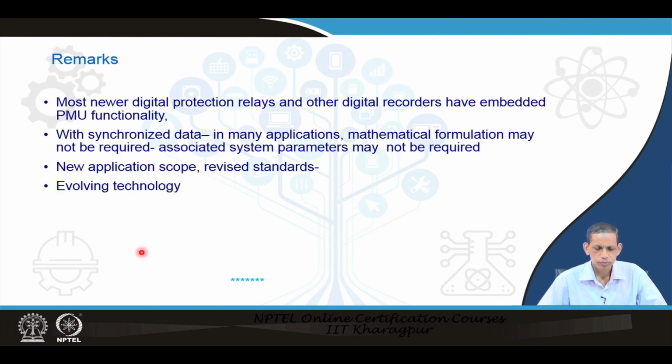So, overall we see that the phasor measurement unit, which provides time synchronized data, called synchrophasors, is a platform where wide area visibility and wide area based protection or control applications become viable with that kind of time synchronized data, which also has time information with each phasor being available.